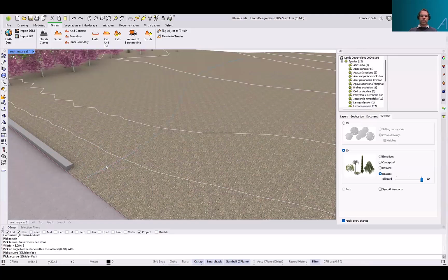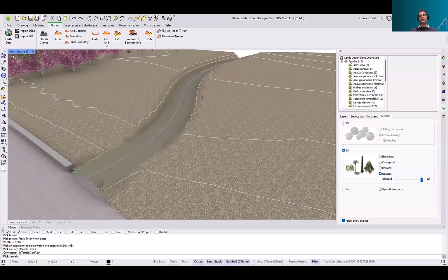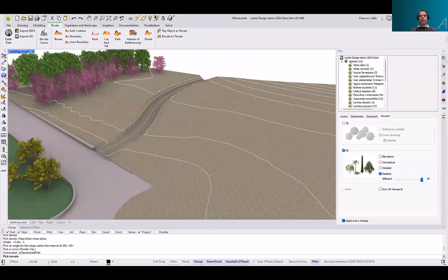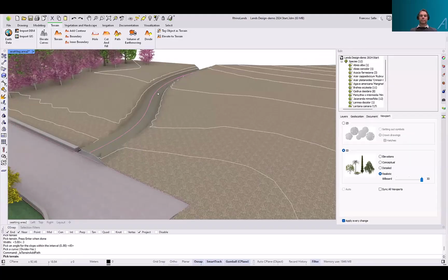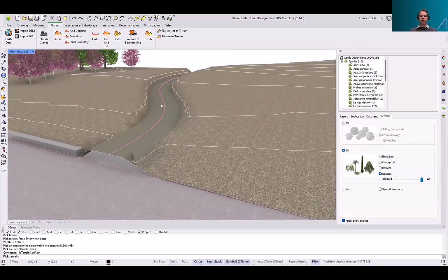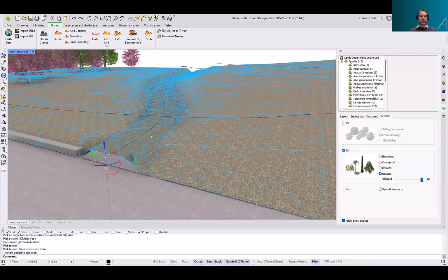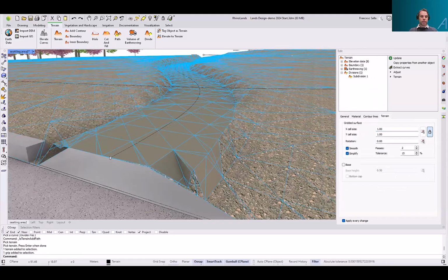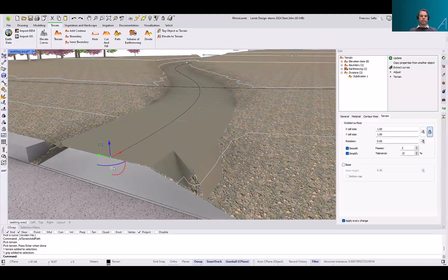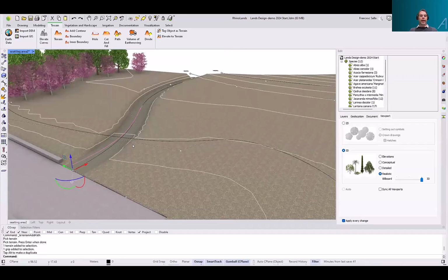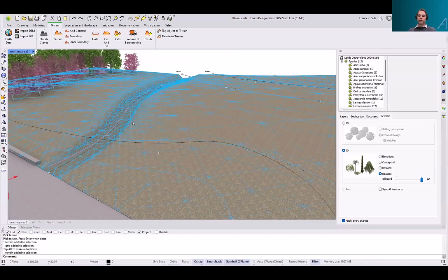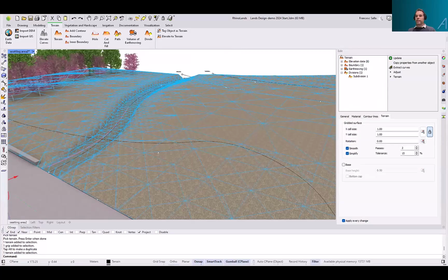This will allow me to change the material assigned to that path. Okay, so now we can see that the terrain has been modified in order to fit with the position of that curve. If we select the terrain, we'll see that we have this control point integrated into the terrain as well. So we can change that by manually pulling this down. Okay. And also, if we select the terrain now, we can see here in the edit panel all the different operations that we have applied.